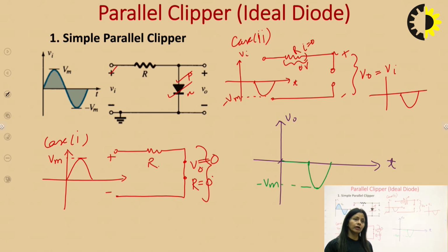It is just that you have to apply the Kirchhoff voltage law, obviously, and be very, very sure how you are taking the diode in forward bias and reverse bias, and you should know the rules. If it is an ideal diode, it is short circuited under forward bias and open circuited under reverse bias. For a silicon diode, it is open circuited under reverse bias, and a 0.7 V battery according to the diode terminal in the forward bias condition, and it will get forward biased after the voltage equals 0.7 or greater than 0.7, right.